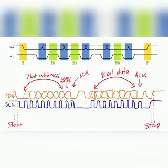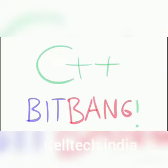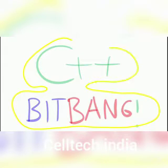At the end of data sending, it's always required that the data line is released for acknowledgement, so the state between data blocks is always going to be okay. I've always found it very useful to learn how to bit bang algorithms so that you fully understand it. So we're going to do that right now. We're going to bit bang the algorithm.